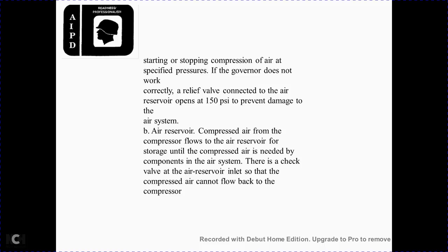The air reservoir stores the compressed air until it is needed by the components of the air system. A check valve at the air reservoir inlet ensures the compressed air cannot flow back into the compressor.